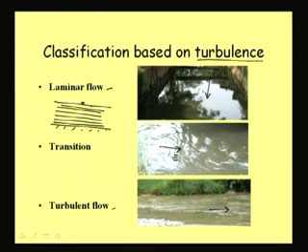And these streamlines, if we call this a streamline, you know from your basics of fluid mechanics what a streamline is. So these streamlines are parallel, and then if I draw a velocity diagram, say the velocity here is this much, and what will be the velocity here at the bed? The fluid which is just in touch with the bed may not be moving at all. So this part we can say the velocity is 0, and from here to here the velocity is changing gradually.